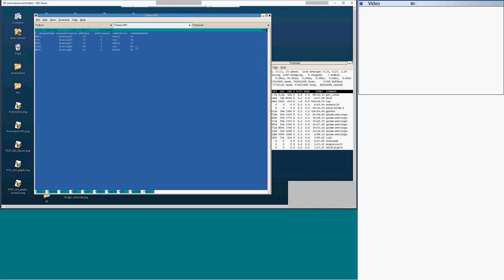In OpenAccess these are real masks, not GDS layers. You may have a single mask when you manufacture the chip, and you can create a single mask from multiple GDS layers. We do support this feature, so we can map several GDS layers into a single mask. That's why we have GDS mapped to mask numbers.